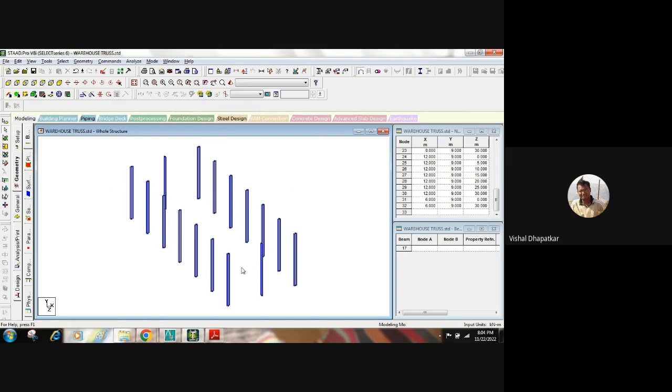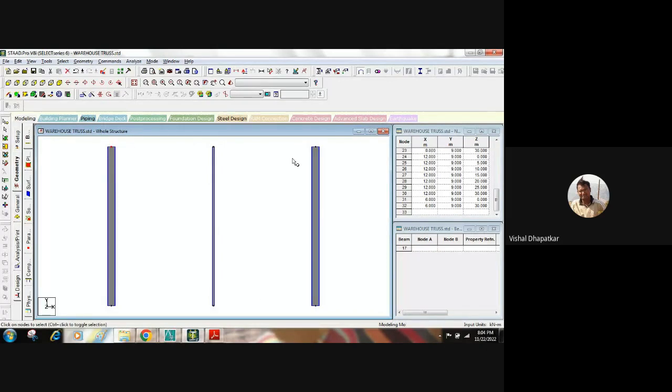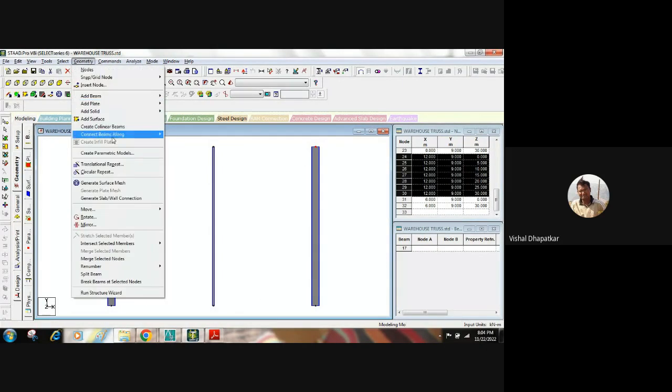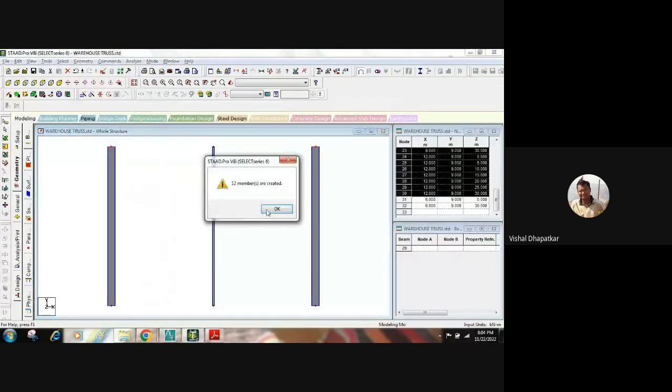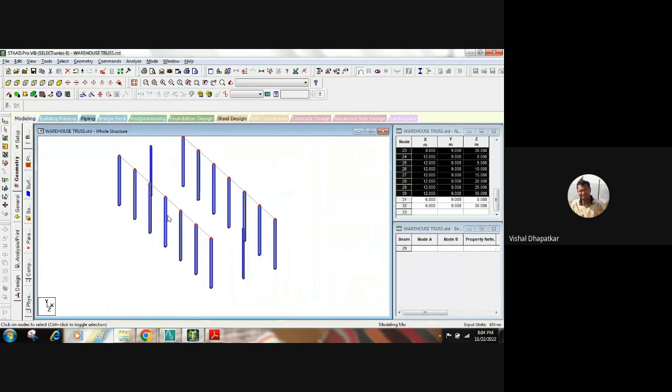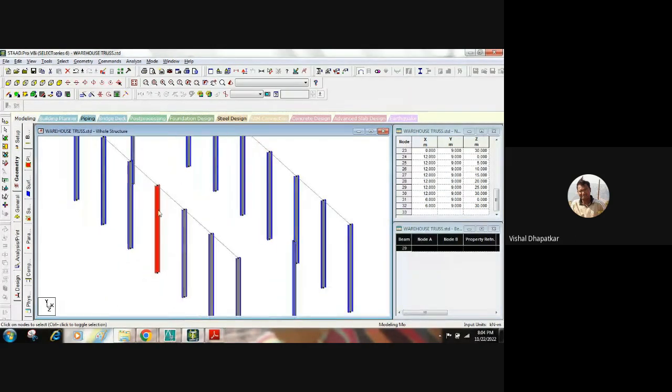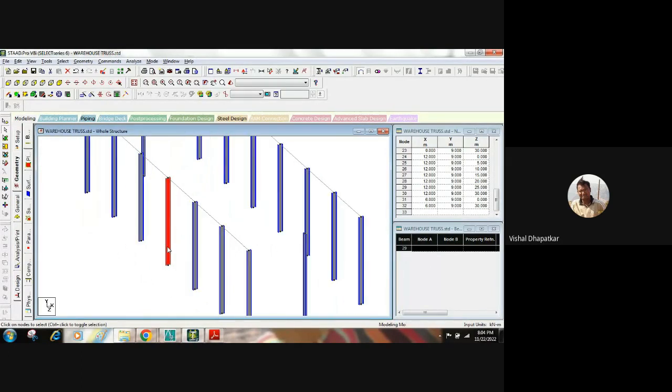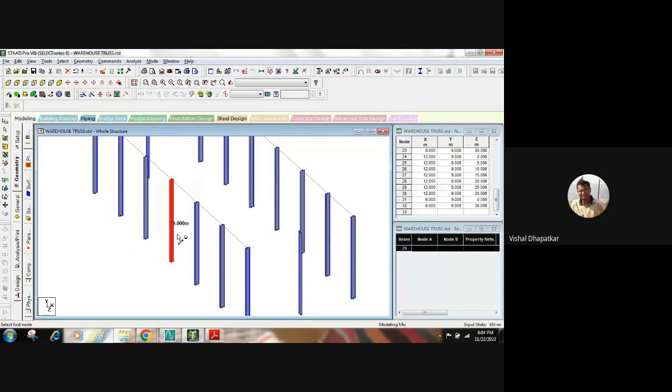Now we will tie all these columns in longitudinal directions. We have connected all these members. Similarly, now this is the minor direction for the column. So we cannot put the column with a complete height of 9 meters when we have the minor axis in this direction. So in order to break its length, we have to provide tie members.